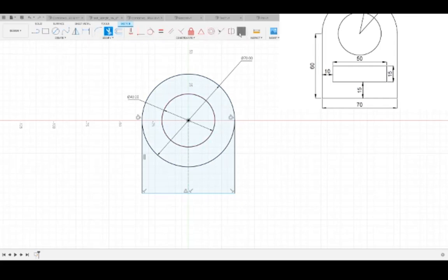Oh, petition to use curvature. Let's give it a shot. I honestly have no idea how this one works. Constrains two or more objects to create a smooth, continuous curvature between them. G2 continuity. So if I selected, maybe it has to be two distinct lines.